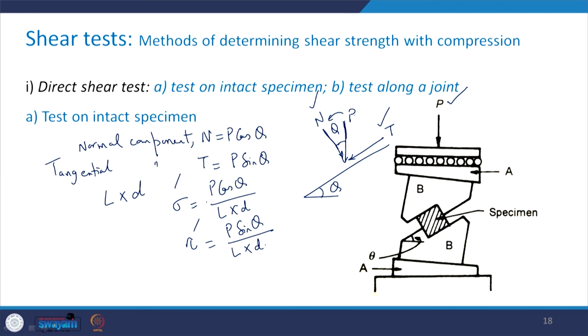So, what we do next is we can plot here tau and then here you have sigma. So, let us say I have conducted say 5 tests. It looks like as if a linear line will fit here. So, accordingly, if it is following the Mohr-Coulomb criteria, I can find out the shear strength parameters like this from the test results.